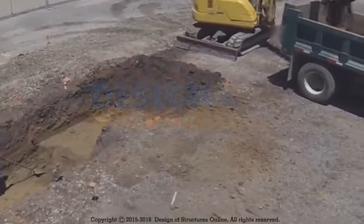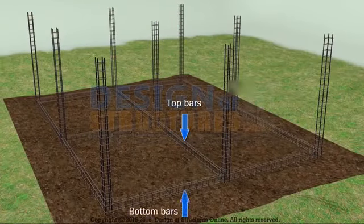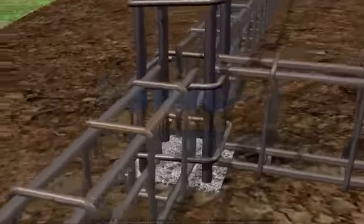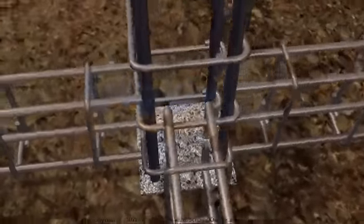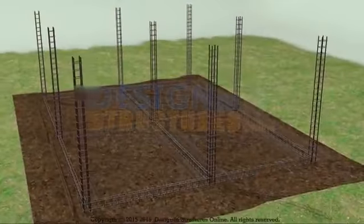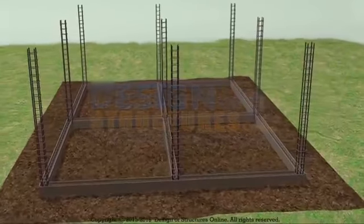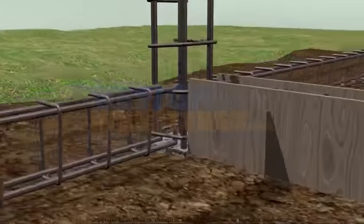Plinth beam as foundation. Beam reinforcement shall be as per drawings. Top bars, bottom bars and stirrups to be placed with proper development length. Joints in the beam shuttering should be tight against leakage of cement grout. Construction of shuttering should permit removal of various parts in desired sequences without damage to the concrete.